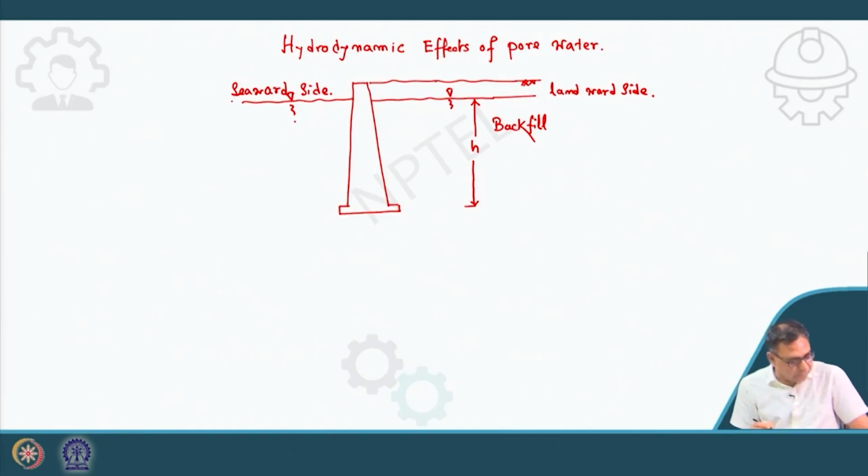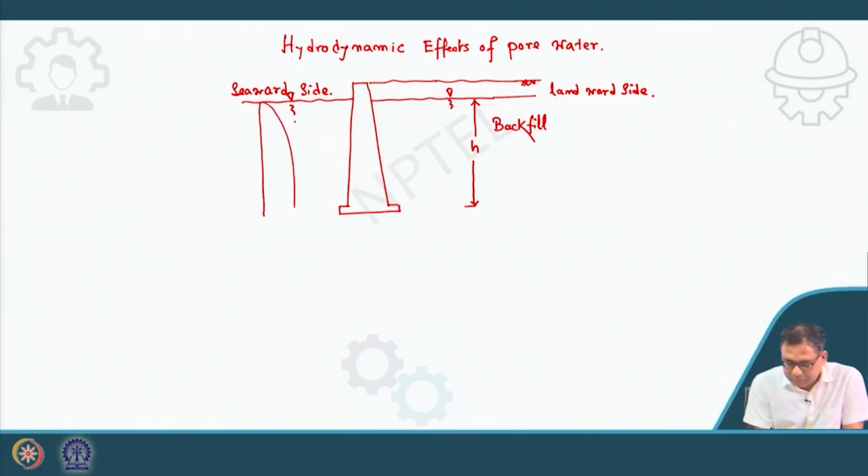We will first discuss the hydrodynamic force on the seaward side, and for this side the variation of this dynamic water force is this one. This is not the dynamic force, this is your water pressure during the earthquake. Say this is H, and this side is also the same H, but not necessarily; it can be a different H value in the seaward side and the backfill side or the landward side.